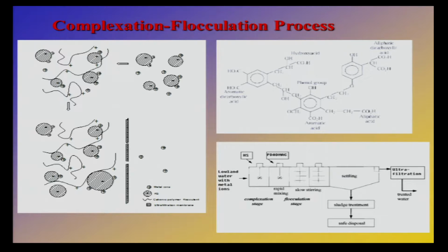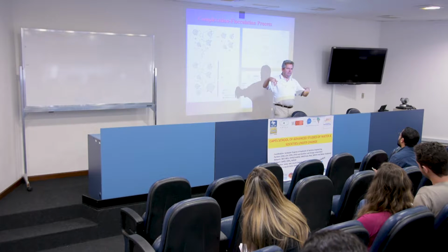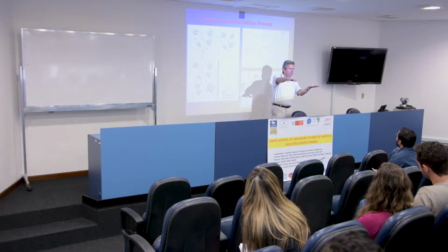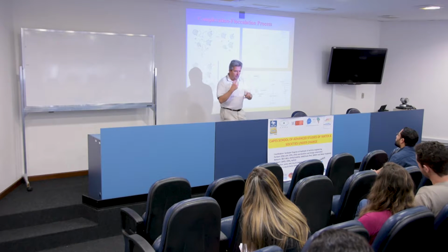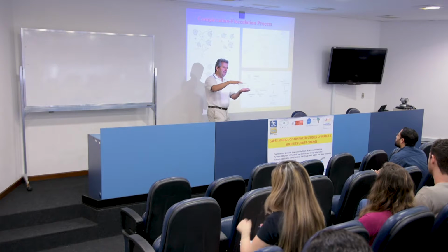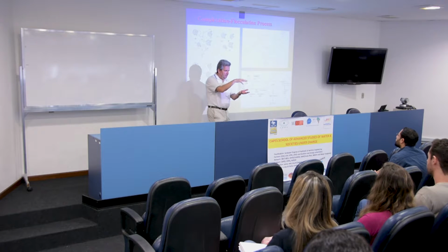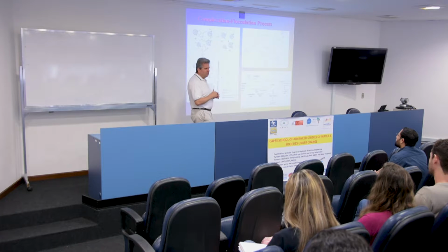And I'm going to put my microphone down so I can explain to you by hand. So when you have flocculation, you have particles that are moving around. And when the fluid is moving very slowly in laminar flow, so we have a very low Reynolds number, the sheets of fluid are moving like this. And as they move, the particles touch each other, and that's how they start to coagulate. So the way that we flocculate things is by using very slow mixing laminar flow to enable this contact to occur and particles grow. So it can take quite a few minutes.